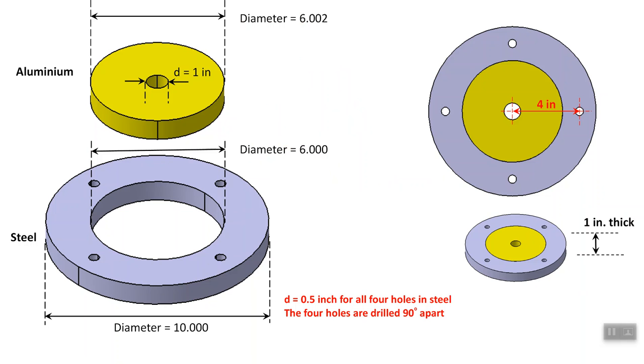It's a shrinkage problem. So there is an aluminum piece which is inserted into a steel piece, and there is an interference fit here. You can see that the diameter of one is 0.002 inches bigger than the other one, and you were asked to use the smallest possible finite element model that you can make so that it represents the entire geometry. Sometimes this is referred to using all applicable planes of symmetry, but probably it's better to refer to it as all finite element planes of symmetry.